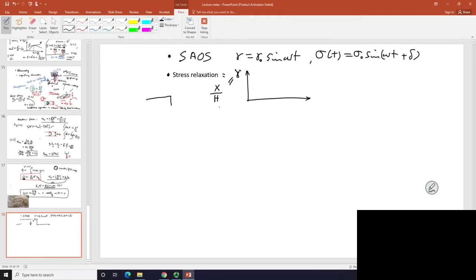So typically, what you do is you all of a sudden move the upper plate a little bit over h, so you achieve a little bit of strain, and that strain, let's say, is on the order of gamma 0. Then your gamma basically behaves this way. It achieves gamma 0 over a rather small time, you build that deformation, and you hold it. That's what you do.